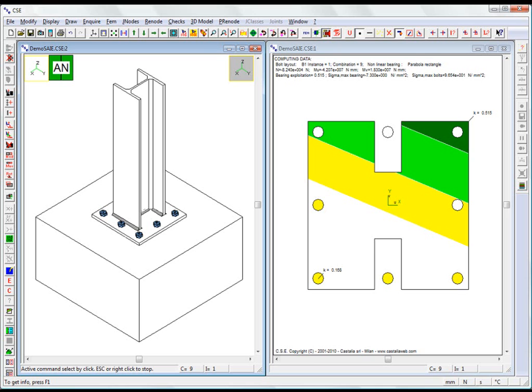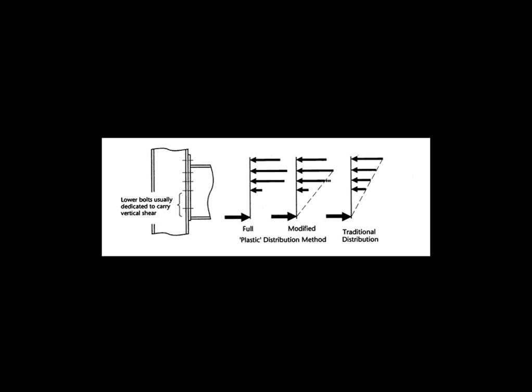For a given bearing surface and number of bolts, the combined tension and bending, or the compression and bending applied, is balanced differently, depending on the uniaxial constitutive laws used for the bolts and for the bearing support. The computation is non-linear. The constitutive law for the bolts is elastic perfectly plastic.